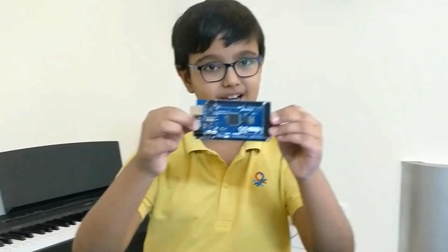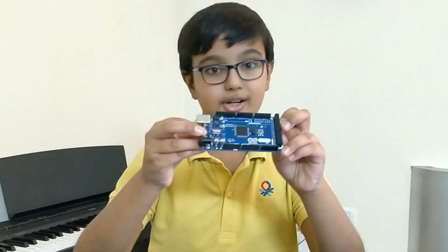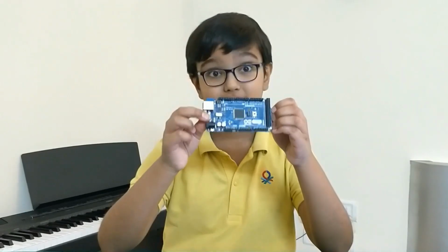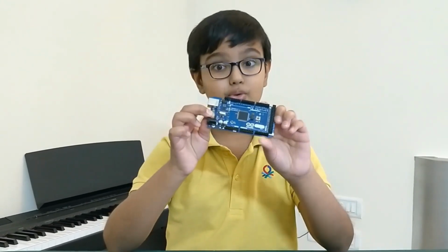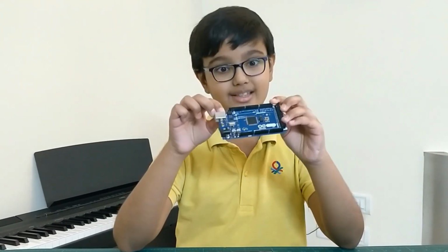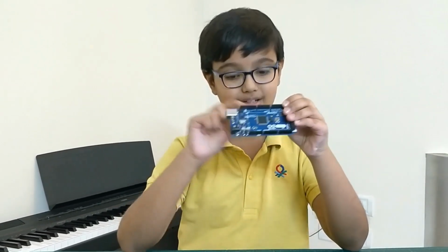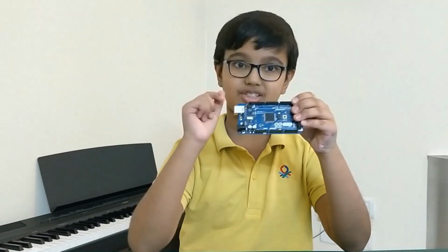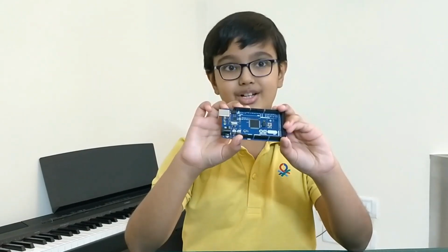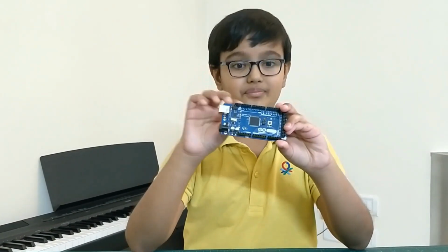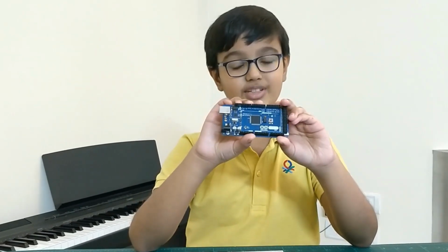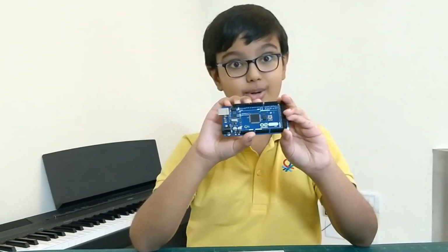We will need an Arduino. We can use any Arduino, and I'm using an Arduino Mega here. But there's one thing to note. If we use an Arduino Uno, we will have to upload the Arduino code first, and then connect the wires from TX-RX to our Bluetooth module, because there's only one serial port on the Uno. But here we are using a Mega, so we have 4 serial ports. The default serial port will be used for uploading the program, and we will be using the serial 1 port to connect to a Bluetooth module.